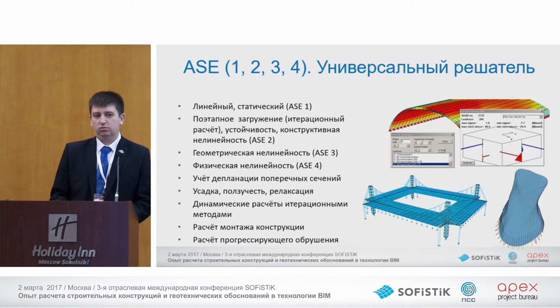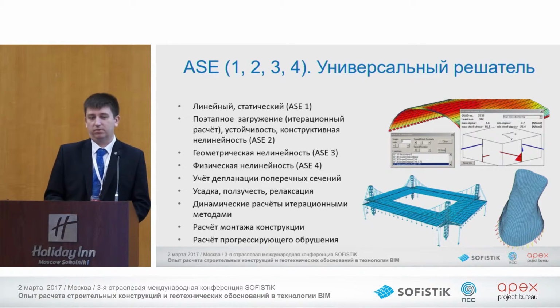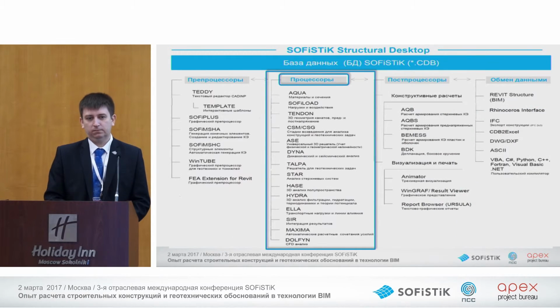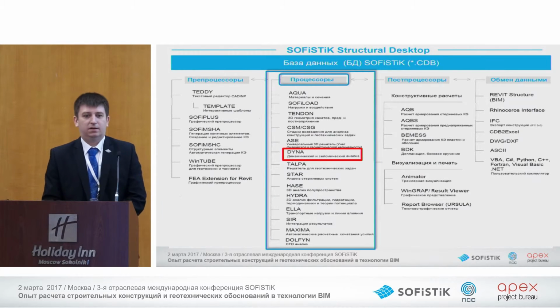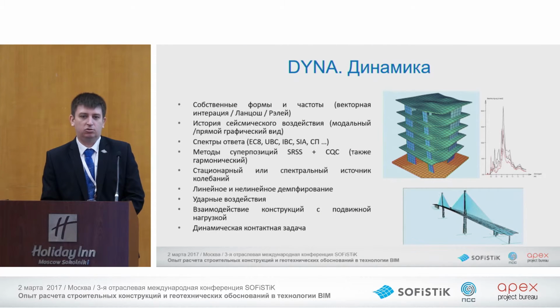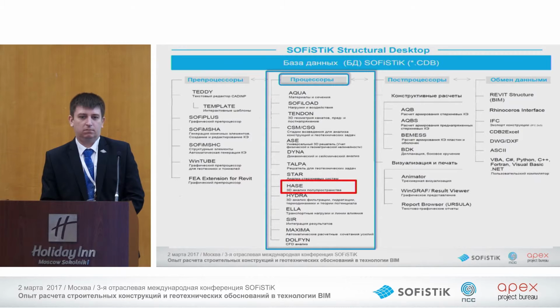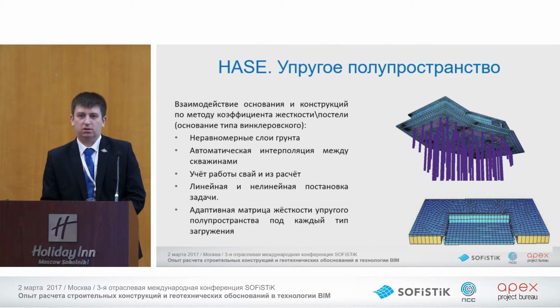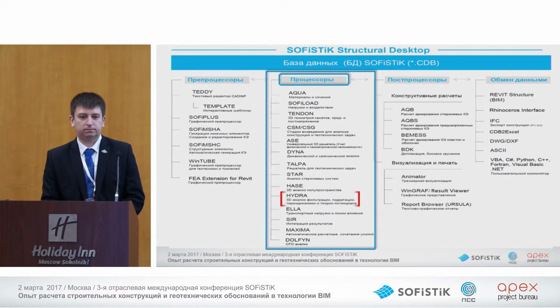Universal Solver, ASE, has options for linear static calculations, for nonlinear calculation, for geometrical nonlinearity, physical nonlinearity, and so on. A special module for dynamic analysis. The next one is for half space to consider interaction between soil and structures, and for several structures in one soil area.